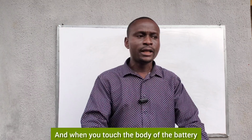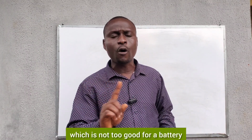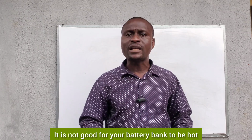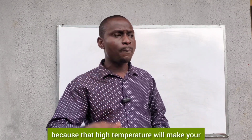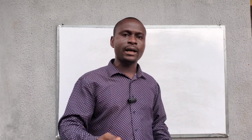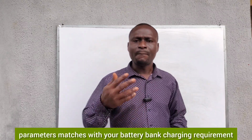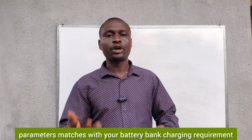And when you touch the body of the battery, it will be hot, which is not too good for a battery. It is not good for your battery bank to be hot, because that high temperature will make your battery become weak. So always check to see that the charging parameters match with your battery bank charging requirement.